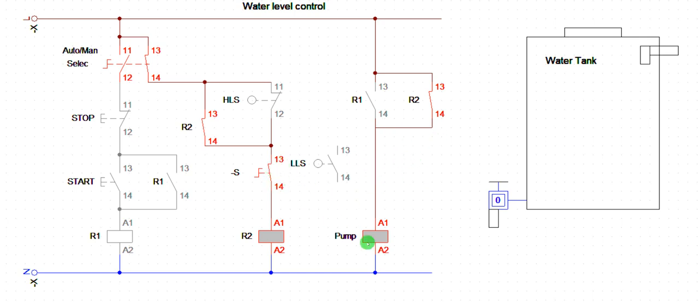Now, when this one is closed, this pump is going to be activated. First of all, when this one is closing, it's going to activate a relay. And this relay now has a contact here to close. It also has a contact here to close. Remember that this other relay has two contacts as well. One of the contacts is to latch this place. One other contact is to close here. So two contacts are an integral part of this relay to perform that activity. The same way, when it's in auto mode, you activate this relay. This relay is going to latch the power here and also latch this place to send power here.